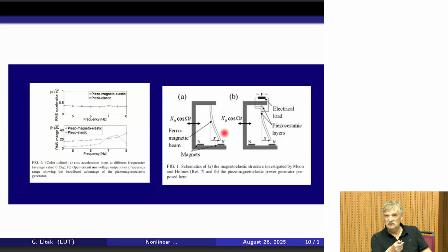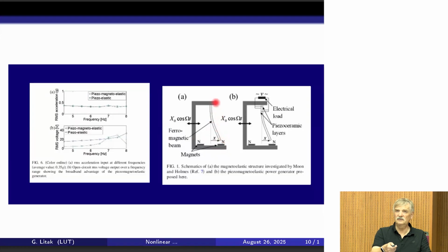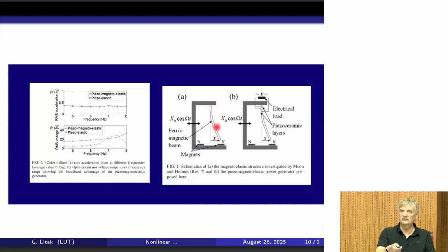It is possible, however, to look at the first mode, because we say that the first mode is when you have only the deflection to left and right, and the curvature is the same along the beam. So if it is deflected to the right, all the points have similar curvature, but not exactly the same.